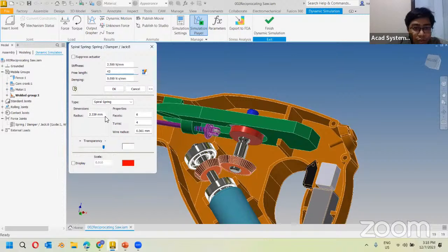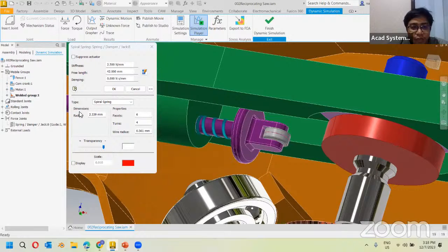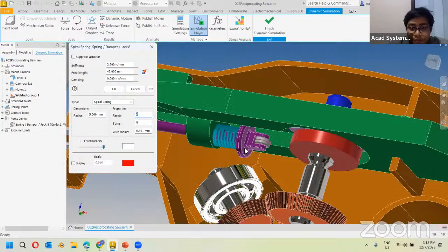And let's say this is a little bit on the appearance of your spring. So the spring will be under 5.2 radius, or maybe just 5 radius. Then the next thing is I can adjust how many turns that I want for the spring. So let's say around 10 turns. So you have 10 round turns, maybe 10 is a little bit too much. Let me reduce to 8.